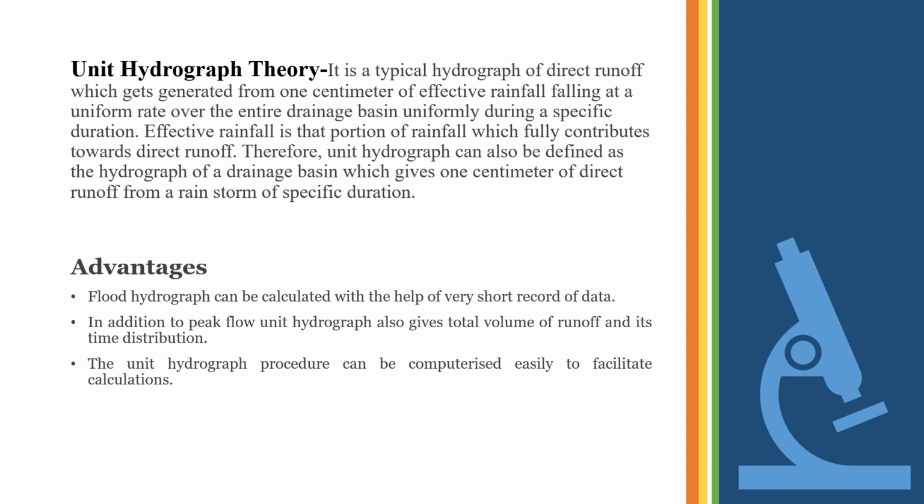Advantages. A flood hydrograph can be calculated with the help of a very short record of data. In addition to peak flow, the unit hydrograph also gives total volume of runoff and its time distribution. The unit hydrograph procedure can be computerized easily to facilitate calculations.